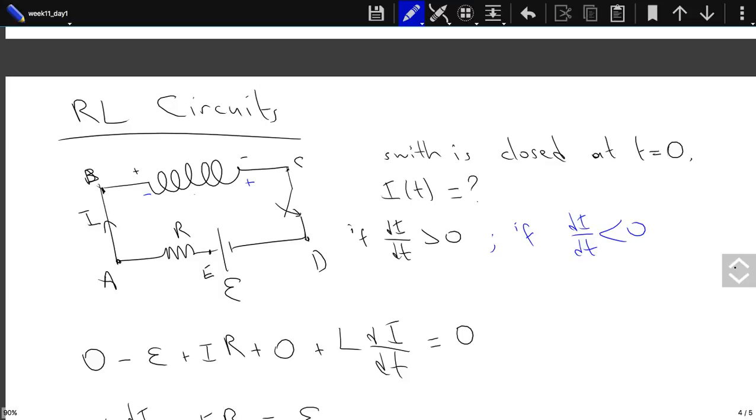Well, it depends on the capacitor, right? As you said, charges will accumulate, which means there will be a potential difference building up. How much charge you can accumulate without creating a huge potential drop will depend on the capacitance of the switch itself. It's not a capacitor, but at the end of the day, it's just two conductors separated by a gap, which is a capacitor. If the capacitance of the switch is high enough, you can actually prevent a spark.